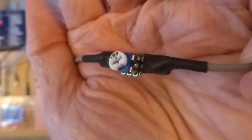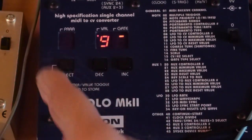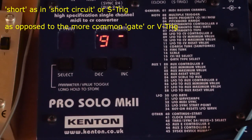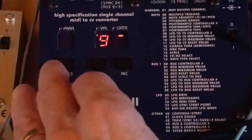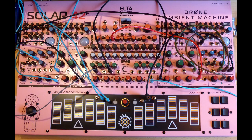Here's how to set up the Pro Solo. Config option 16 defines the gate type, which offers combinations of short trigger versus gate and 5 volts versus 15. So set this to gate 15. So the special cable can drop this to 10 volts. Connect the other end to VCO-A's gate input and connect the CV output to VCO-A's 1 volt per octave input for the pitch.